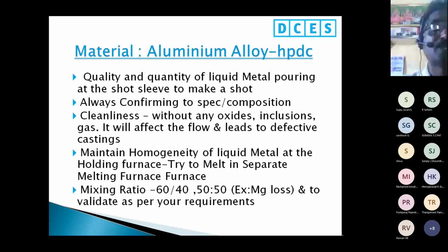So the final pressure won't be there, and we will have a solidification shrinkage. That's why both are very important. And always conform to spec and composition. Every time, not necessarily checking every pouring, but in between have to conform to the specification. The cleanliness, without any oxide and inclusions or gas, affects the flow and leads to defective castings. Maintain homogeneity of liquid metal at the holding furnace.